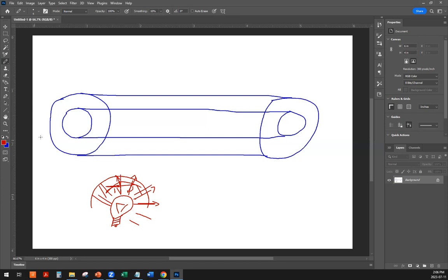All right, so let's say we have a different number of modes, because this is multi-mode. There will be a laser diode or an LED emitting light and shooting the light into the core under specific types of angles, so it's not going to exceed the critical angle. So the light just keeps traveling in the core. It doesn't escape through the cladding.